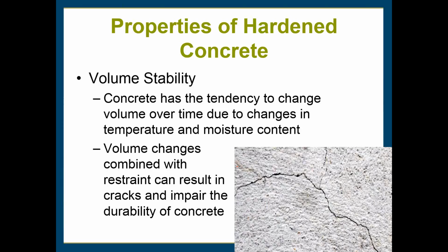So when you have restraint, in this case we're referring to rebar in your concrete. Steel and concrete will change volume at different rates when they are at different temperatures. So that can sometimes have some negative effects on your concrete and result in cracking.